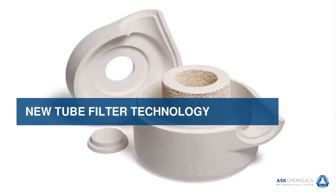All the filter installations listed above have one very distinct and serious similarity: the risk of filter breakage. This is the worst case scenario of filtration applications, which often leads to the scrapping of the affected casting. It was therefore the task to avoid this case and to design a filter which provides reliable protection from this occurrence. To reduce the risk of breakages and to make it safer, the tubular filter for use in steel and iron applications was developed.